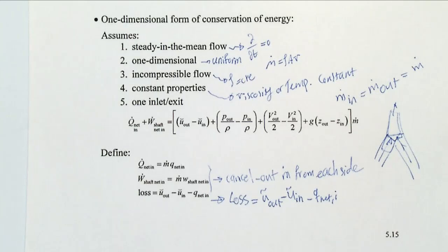Okay, so Bernoulli's equation by itself is for when you don't have any loss. The other assumption that we forgot about, I couldn't remember, is viscosity. So we had another assumption in Bernoulli that the flow is inviscid, right? What does it mean that the flow is inviscid? It means that you don't have any loss of energy because of friction. So when you don't have any loss of energy from friction, you don't have any Q net.